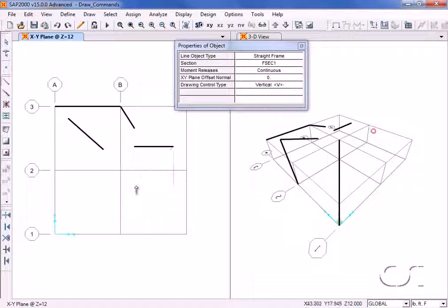Similar controls available if we hit the V key or A. Note that the angle is 45 degrees. And L, which draws a fixed length object. Clicking the Set Select Mode button exits the draw mode.